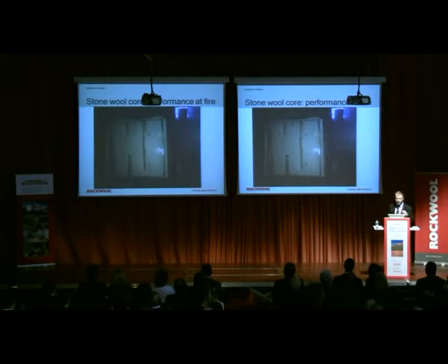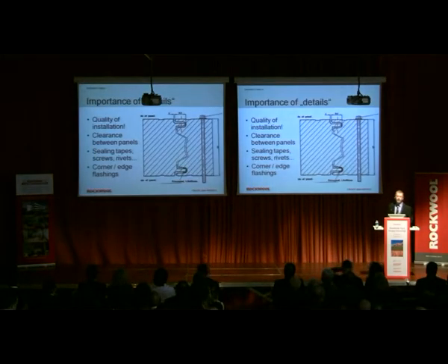On the contrary, if you look at the stone wool core sandwich panel, this is a picture of what happened after 1 hour of fire testing. We have almost no smoke here. There was some small failure here, a very small flame which died out by itself, but nothing else. So it is a completely different level of danger. Fire safety is always about danger, about risk. You can never eliminate this risk, but you can do what you can to decrease it.